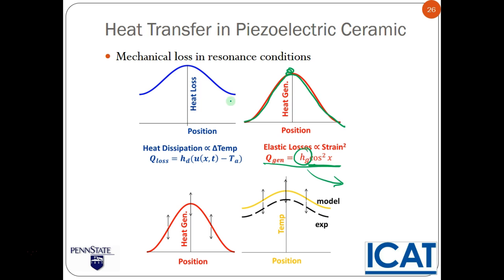And the heat dissipation, because conduction occurs, if heat is generated here, it's going to want to flush out and even out. Because the heat wants to be even, it's going to transfer itself to the edges of the ceramic over time, through heat diffusion, heat conduction. So as the temperature of the edges increases, heat loss will also increase. Heat loss according to convection is proportional to the difference between the temperature of the material or the transducer and the outside temperature.